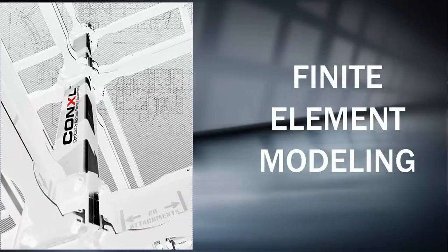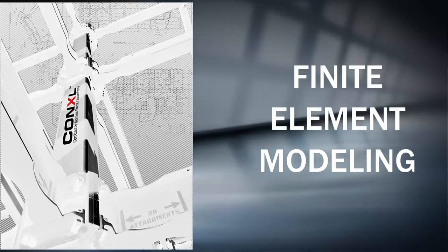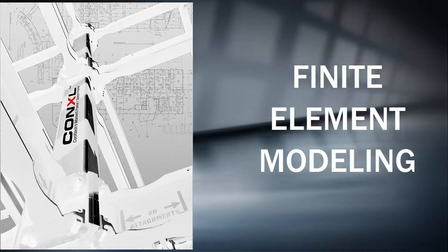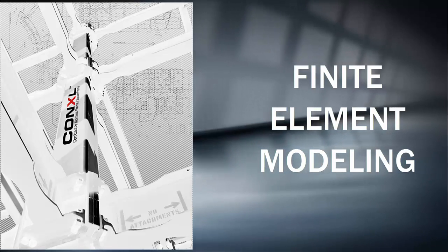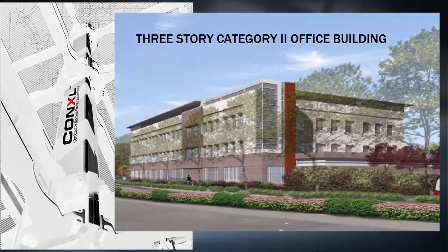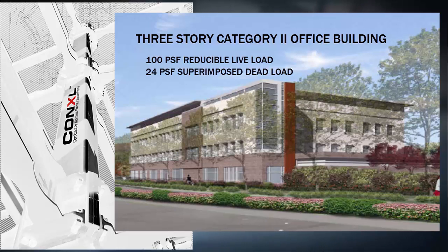The following example is intended to illustrate the basic steps required to generate an initial model of a building using the program ETABS. We will examine a 3-story Category 2 medical office building. We will use 100 pounds per square foot reducible live load on the floors, 24 pounds per square foot superimposed dead load. For seismic design, we'll use S sub S equals 1.5, S sub 1 equals 0.6 with a site class D.